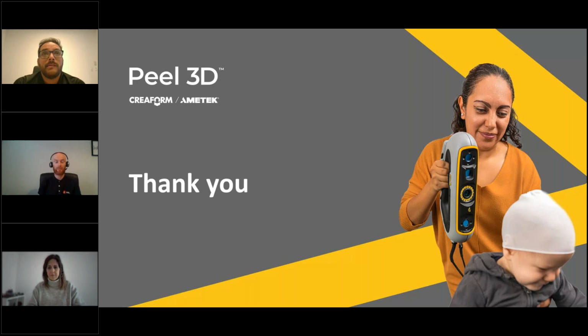If it's being 3D printed to make a mold, or if you need to make the interfaces for that mold into a CAD model, then it would be a case of extracting those interfaces from Peel.cad, bringing them into SolidWorks to create your STEP or IGES model from there. We can also extract CAD surfaces from Peel.cad, so if you've got complex surfaces that you're trying to model, maybe that's a simpler way of doing it, rather than trying to recreate those surfaces from sketches. But it would really depend on that workflow that goes into creating your mold.